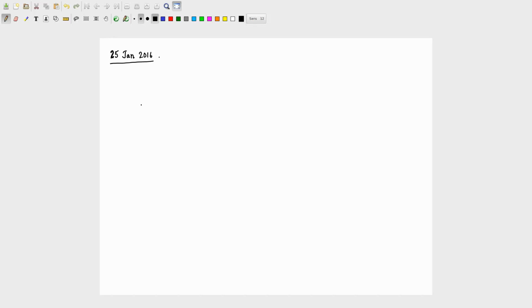So in last class we had discussed the form of the Y matrix that will give us an ideal voltage controlled current source. So we saw that to get a nice voltage controlled current source implies that I want a Y matrix of the form 0, 0, some gm and another 0.